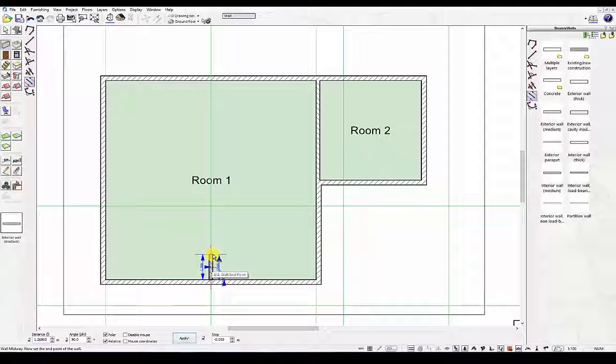Step 4 is similar to step 3, but here you will now set the end point of wall. Before placing wall in position, use the key combination Ctrl and W to toggle between the wall edges and wall axis. This lets you define which wall edge to place in relation to the reference point, for example the inside edge of wall, center line of wall or outside edge of wall. Try pressing this key combination a few times to see the effect on the screen.